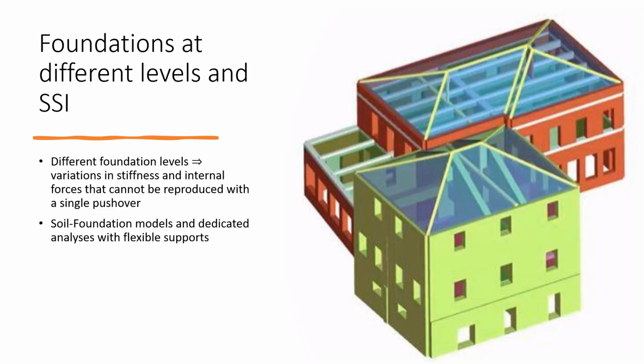Other cases of, let's say, controversial use of pushover analysis are buildings with foundations at different levels, and or cases where soil-structure interaction is very, very relevant. In the case of different foundation levels, there are significant variations in stiffness, and internal forces cannot be fully reproduced with a single pushover. We probably need to use different pushover analyses and check whether some simplification is appropriate.